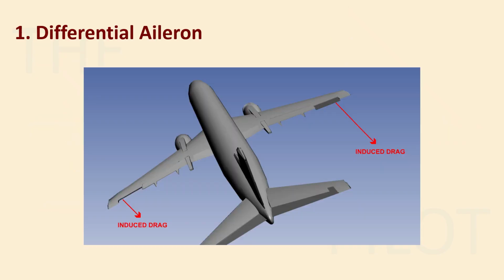So see how we reduce it. What we did was move this aileron downwards by a lesser distance. So induced drag was there, no doubt, but the parasite drag that was also adding to the total drag was reduced. The parasite drag is reduced here. And on this side of the wing, we have moved the aileron upwards by a larger distance, which means what?